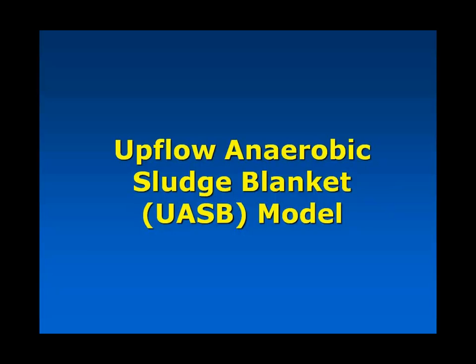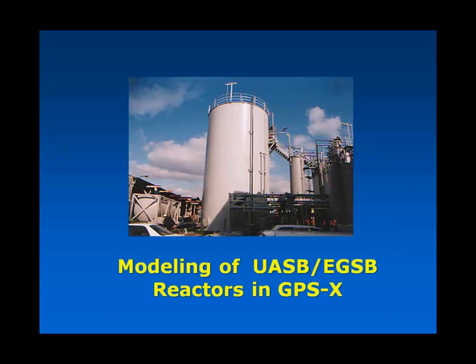But as part of a project we were working on, we developed a really rigorous, very robust UASB model that's easy to use. We liked it quite a bit, and we put it into GPSX, and it is now available. Modeling a UASB reactor is a fairly complicated system. There's actually a lot going on there compared to just modeling a conventional, completely mixed activated sludge tank.